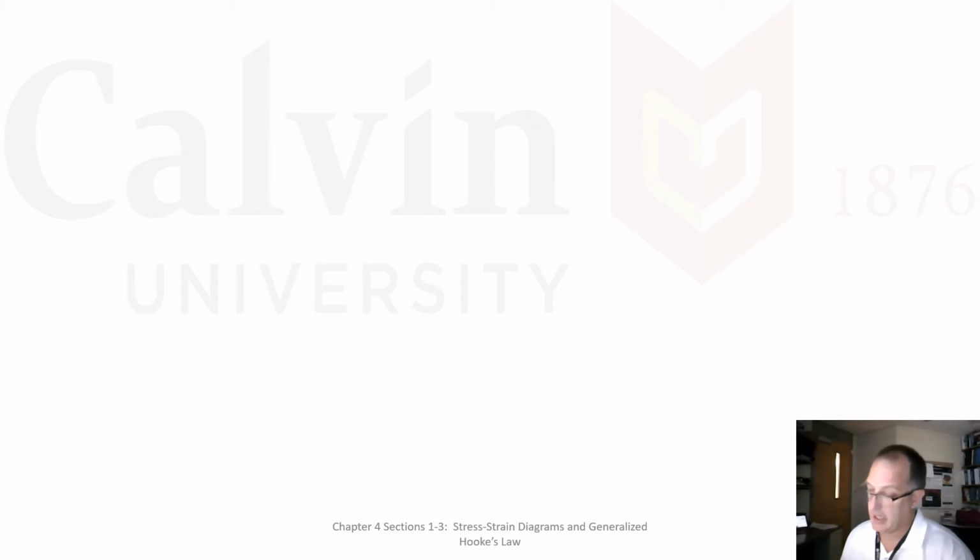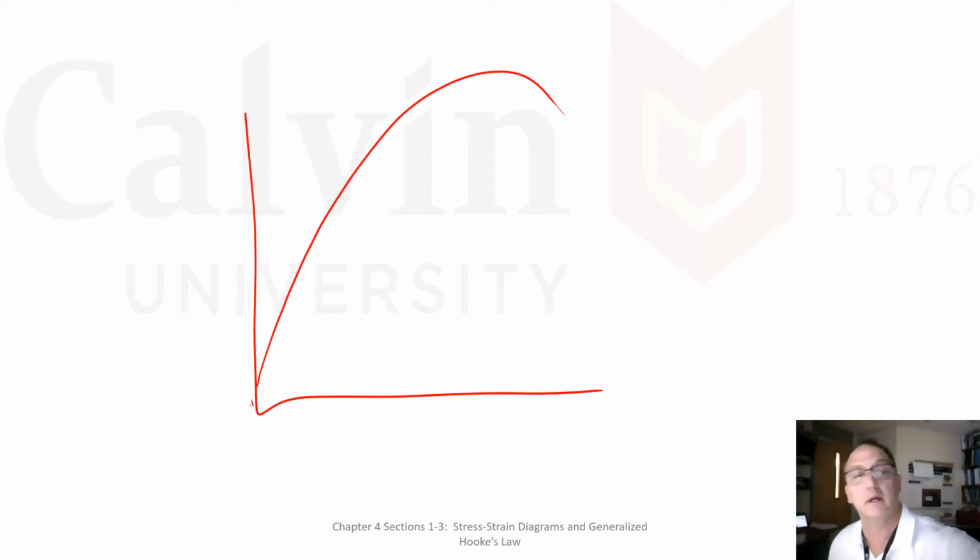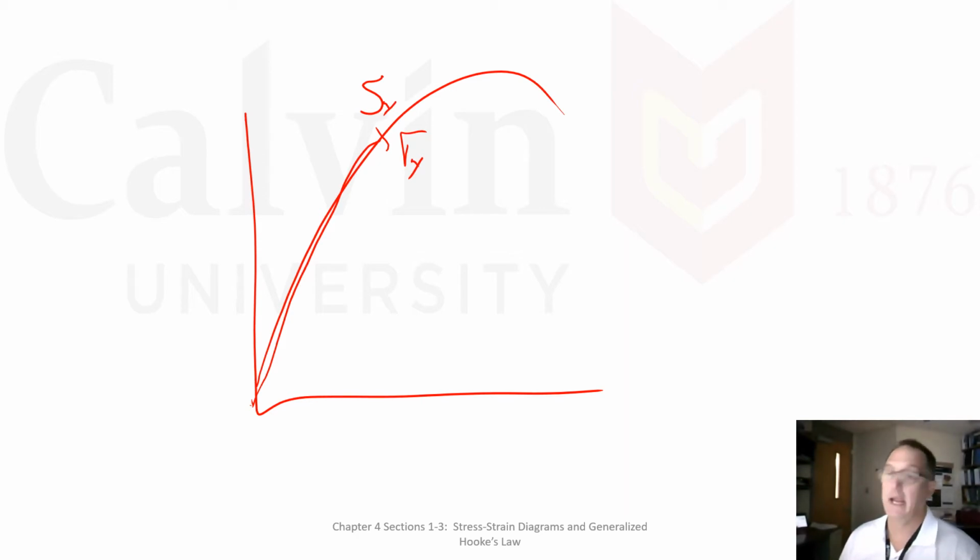as we start out, I want to talk about this material chart. What we know coming out of this is we got some material properties, and we defined a point here, which is S_Y or sigma Y. It's a strength, and the Y denotes that it's a strength or a stress, and it denotes the yield point for the material, where it starts to plastically deform.